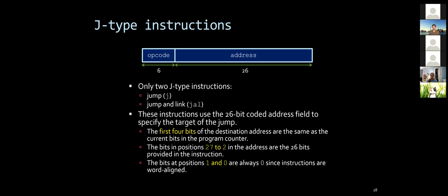Yes, longer jumps. If I'm going to use a small 16-bit offset constant, I would always stick to a very small segment, right? I cannot go too far. So I need long jumps to go to further addresses. But they are more rare. Most cases, say within a loop, we don't even need that.